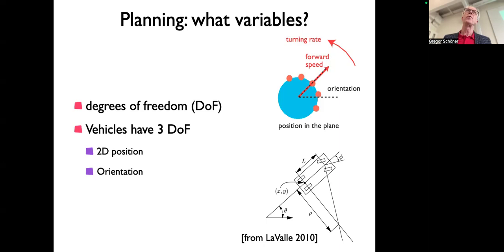So 6 is just mathematically or physically the degrees of freedom of a rigid body. And we will be studying the degrees of freedom of robot arms when I talk about kinematics in the second half of the course. And we'll then actually argue that robot arms consist of many rigid bodies chained together. And these chains and the joints restrict the degrees of freedom, typically to just 1. A hinge joint has just 1 degree of freedom. And so typically you will have a robot that has actually 6 rigid bodies, each one restricted to 1 degree of freedom through that hinge joint, so that together, again, they have 6 degrees of freedom. That's most robots, like industry robots.